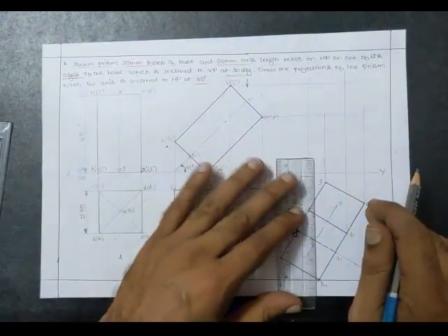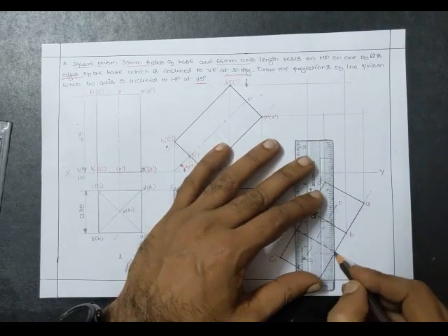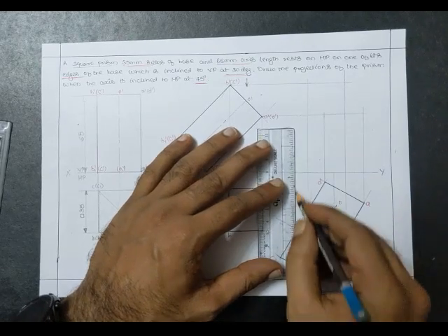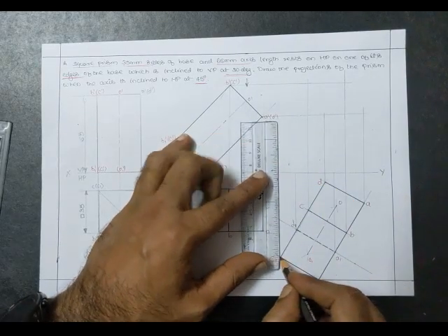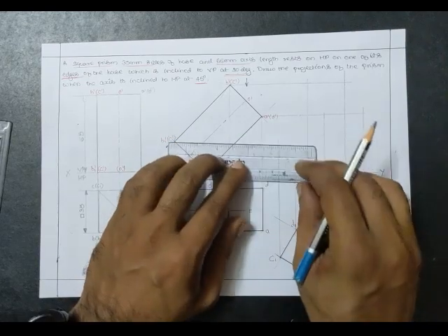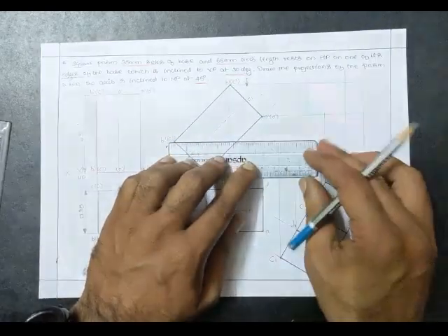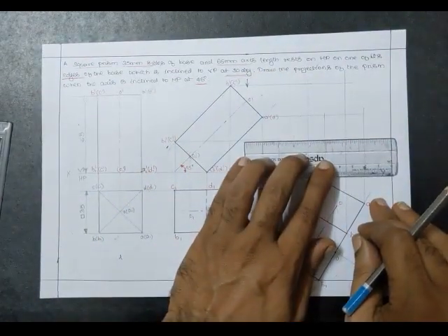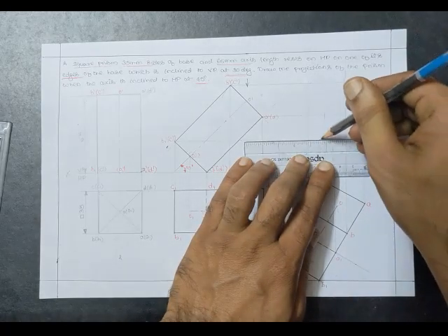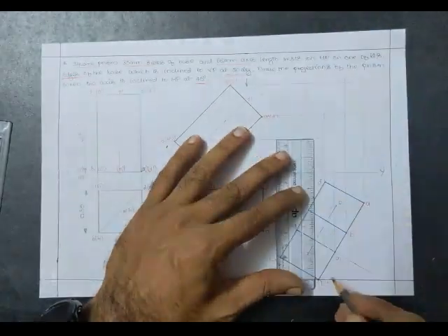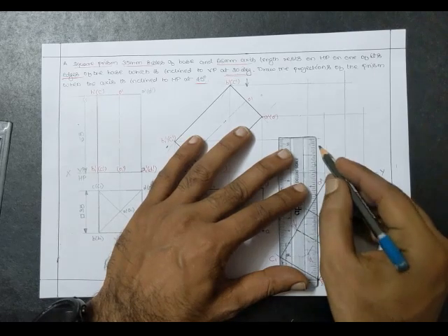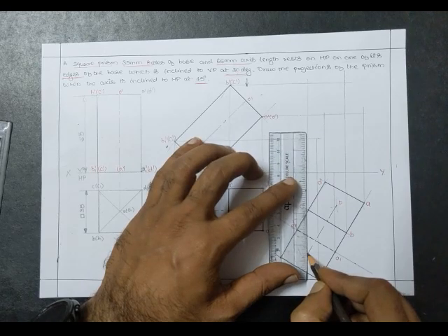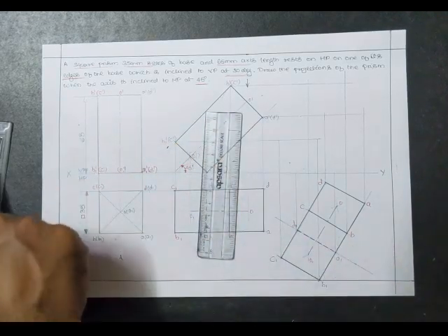So I got the top side, and let me go with the base. This is the resting edge, so it should be on XY line. So corner A1 is done and corner D1 is done. So let me go with C1. Look at where is C1. So according to that, you need to draw the projection. You should be very, very careful. You need to draw the projections so that nothing is wrong. So only required points should be drawn very carefully, and also the axis, if you want it. So let me think of that later.